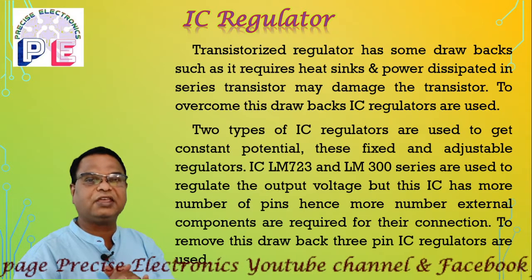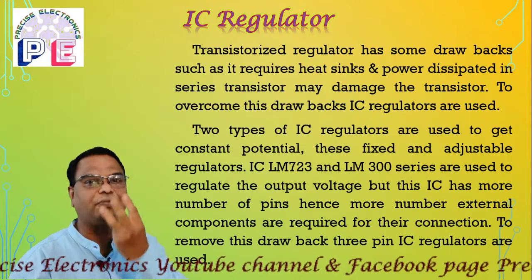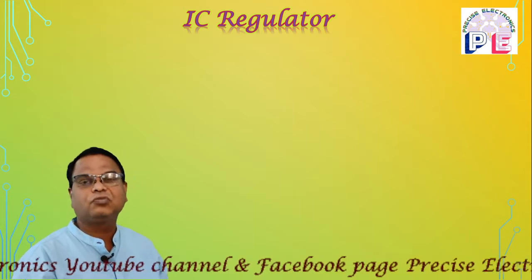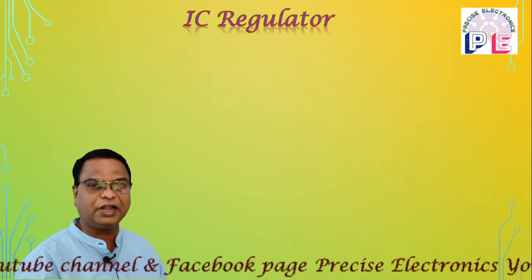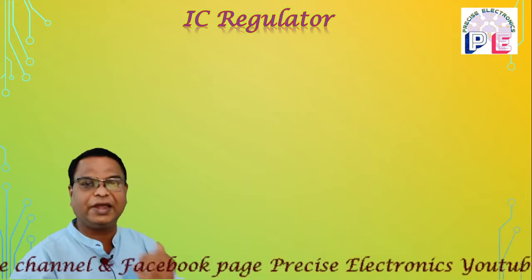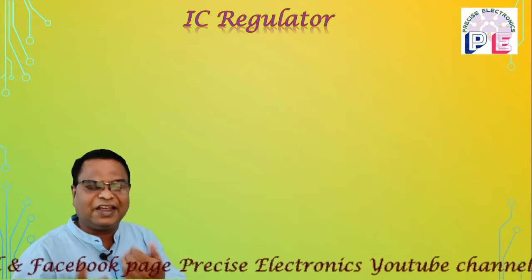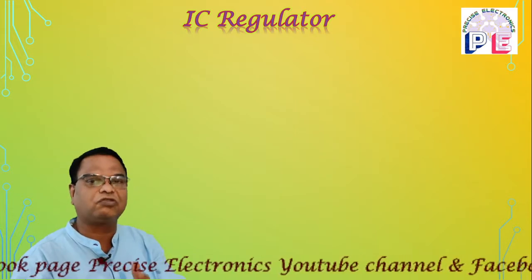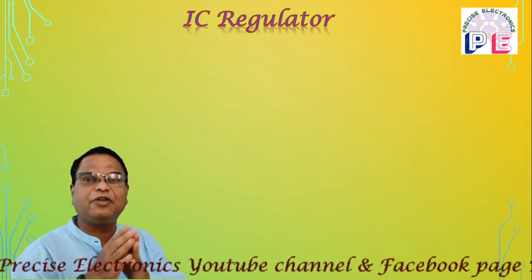This drawback is also removed by using the next type of regulator, that is known as the 3-pin regulator. Friends, the 3-pin regulator has only 3 pins. One pin is used for the input, that means the input signal which has to be regulated is applied to that pin. The second pin is the common, or it is also known as the adjustable pin, because there are two types of IC regulators, fixed regulator and variable regulator.